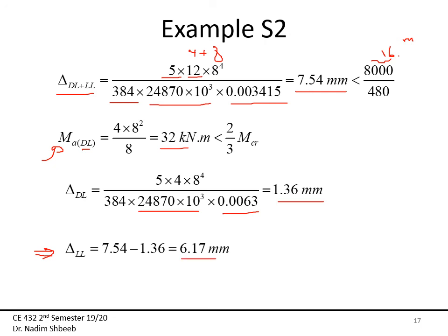7.17 millimeters. Okay, here I'd like to point out, if I was asking you what is the long-term deflection after 5 years, for instance, then you still have to do the same steps, because in that part, the delta long-term, and we know we don't have any compressive reinforcement, so that rho prime now is equal to 0, right?